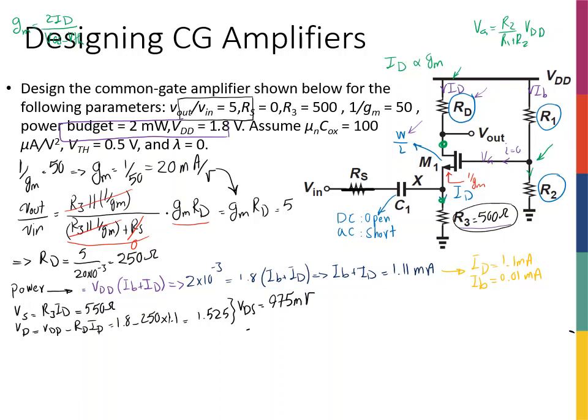Okay, so now I got my VDS. I have to first calculate my VGS to make sure that my transistor is working in the saturation region. How do I do that? Well, I know that up here I wrote GM is equal to 2ID over VGS minus VTH. I have GM, that's 220 milliamp per volt. I have ID, I have V threshold, I can find VGS, right?